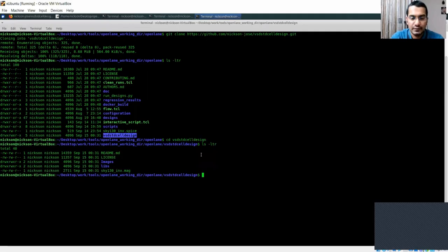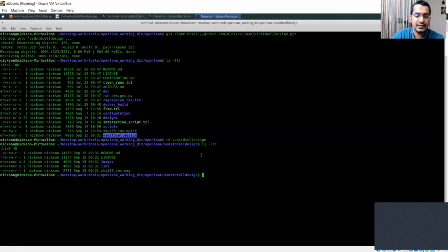The quick way to do it is to click on this line and just zoom in. If you zoom in over here, this is the point where this curve is intersecting with the 45-degree curve, and that point is somewhere at 0.99 volts. So your switching threshold is equal to 0.99 volts. Your rise delay is 148 picoseconds. Your fall delay is 71 picoseconds.